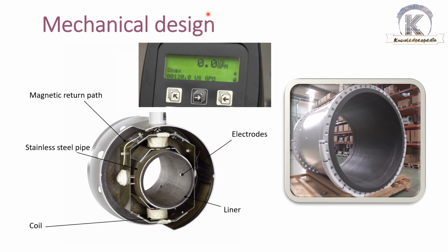More importantly, however, no moving parts or obstructive surface to wear usually translates directly to a longer service life and an overall good investment. Whatever you are investing, you will get a good return because it's a very long life flow meter. In addition, the flow meter is inherently bidirectional, as I already explained. This can be a tremendous cost saver for many applications.